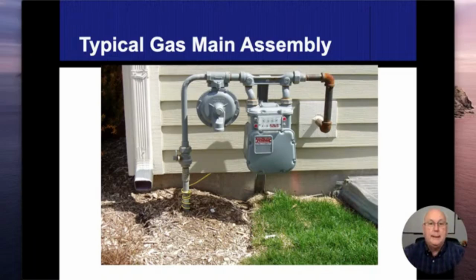One of the questions I like to ask people when they start in this business is, should we ground our electrical system to the gas pipes? A lot of people look at me like, what, are you crazy? No, because if there's a spark, it's going to explode. That's not the right answer, all right? If we have 100% natural gas, it's not going to explode, even if I start getting sparks to it. If I have a leak, that's a problem, and any spark nearby that leak can create it, but a grounding isn't going to do that. The main reason why we don't ground at the gas pipe is because it's plastic. I don't get a good connection to the earth.